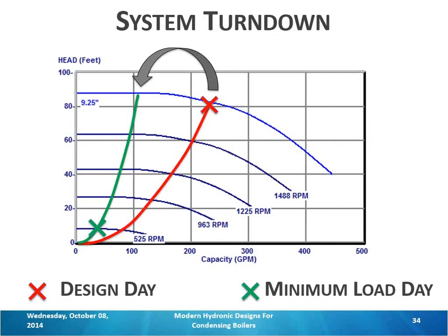So on our mild day, we only need 1 boiler at its minimum firing rate of 20% input. We're supplying 100-degree water with 70 degrees coming back. Only a couple zones are calling, and our bypass is cracked open to relieve some of the pressure on the pump. Any questions at all?